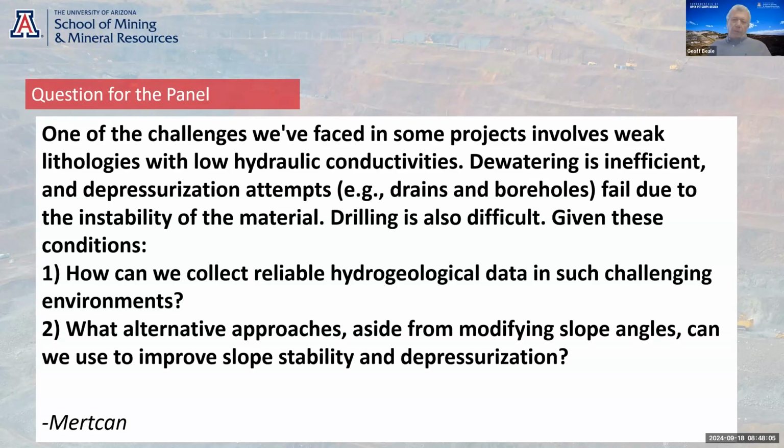I think, Travis, weak materials are actually more sensitive. There's more benefit in depressurizing weak materials. Weak materials tend to be more sensitive to water, so it's worth making the effort to do so. Yep, absolutely. It somewhat depends on the scale of the problem too, right?